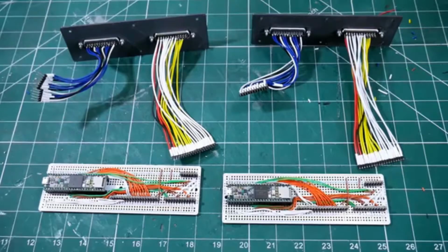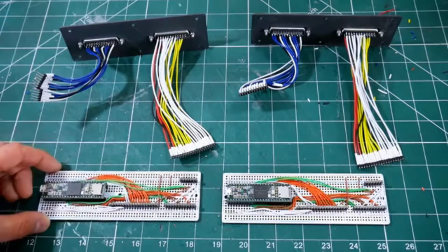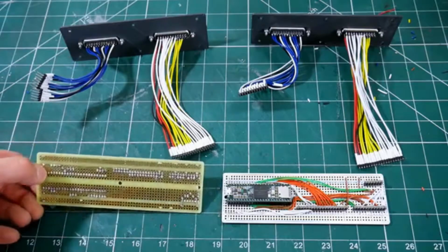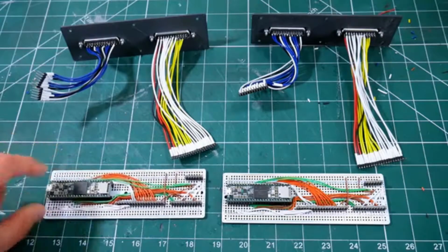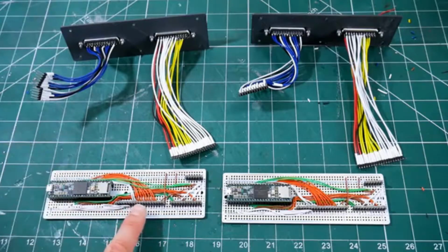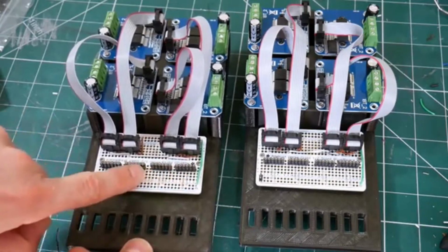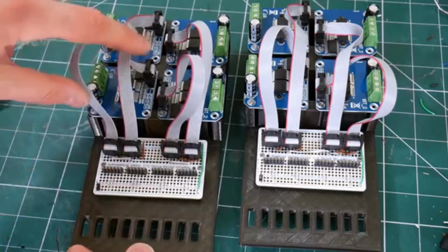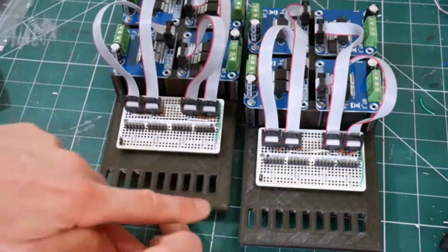So the main control system for the robot is a Teensy 3.6, and I've got this on Perma Proto board, which is made by Adafruit, and that's basically a breadboard solder board, so it's really easy for prototyping, especially for dual inline packages. So there's lots of PWM ins and outs here, which will be for reading. Obviously we've got the breakout again here, we've got the motor encoders that'll be plugged in there, and the wires that come back to these motor drivers, and so we'll wire everything to this board and strain relieve it on here with zip ties.